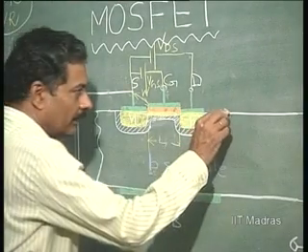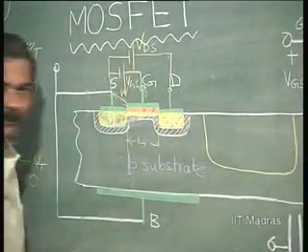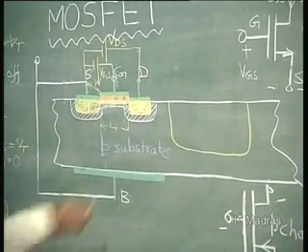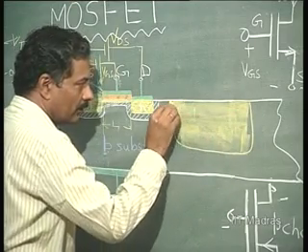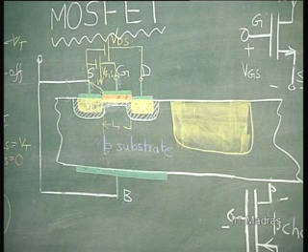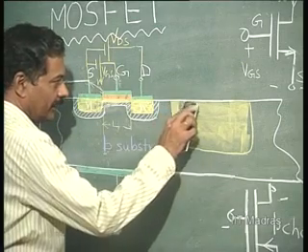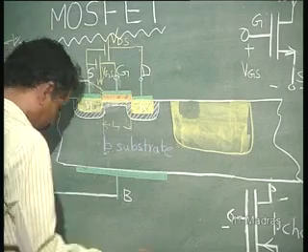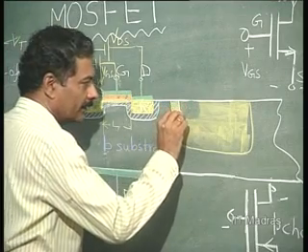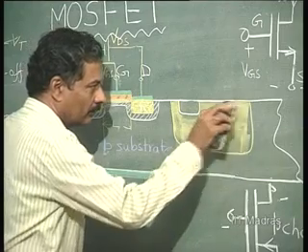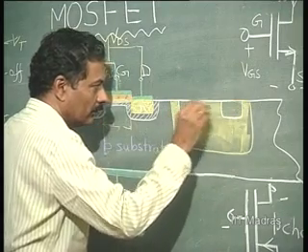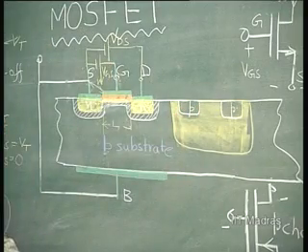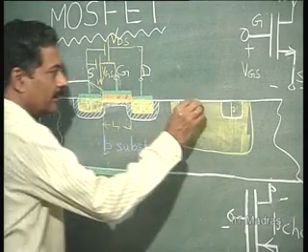And I would like to have a P channel FET also in this, then I will have an island of this diffused region to formulate a P channel FET, in which I will now diffuse P type impurities as source and drain, and then we will have a similar gate like this.